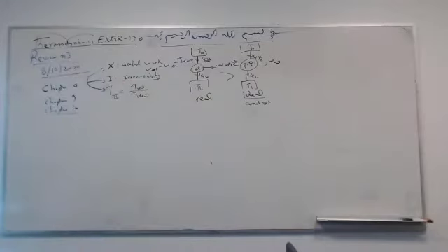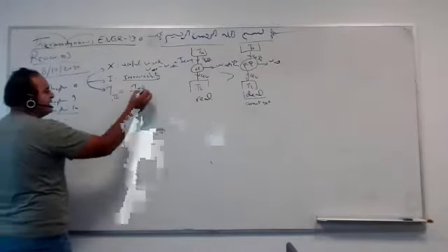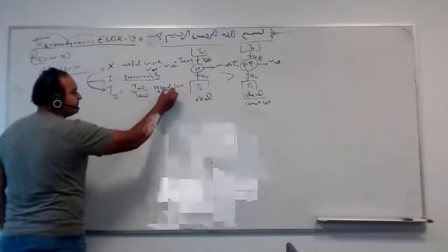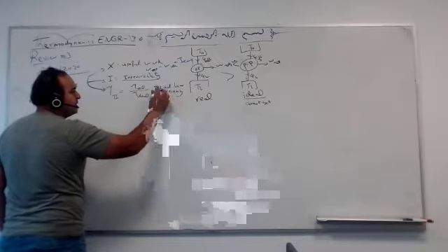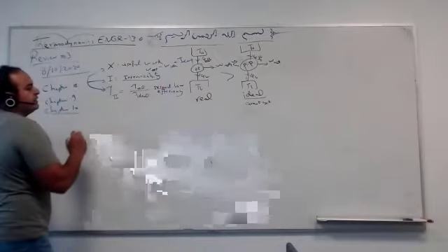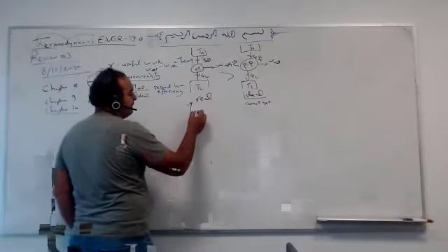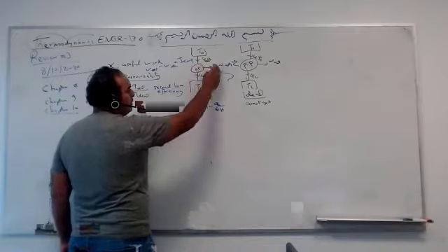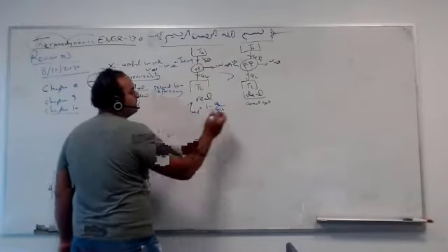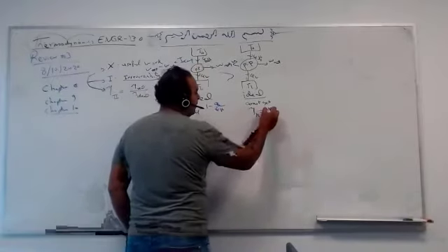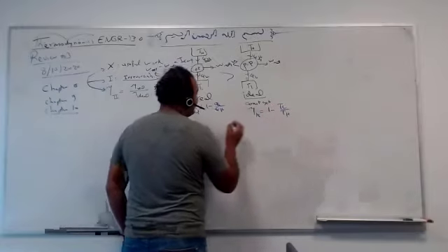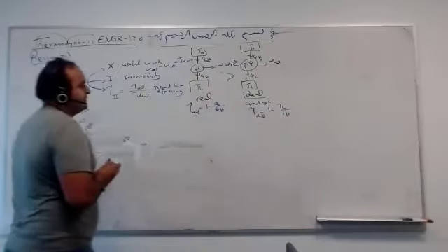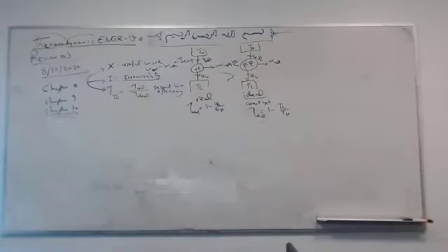If we talk about a system or even a component, the second law efficiency is eta real over eta ideal. For example, eta real here is 1 minus Q low over Q high, which is actually W net over Q high, output over input. Here, it's just 1 minus T low over T high. This is real, this is ideal. Both of them are thermal efficiency. Okay, guys, this is the summary of chapter 8.